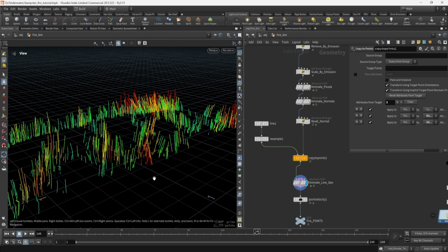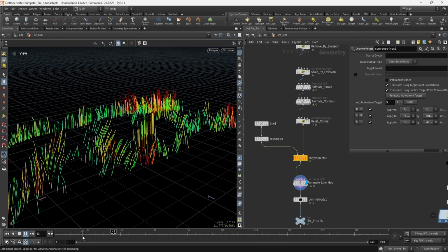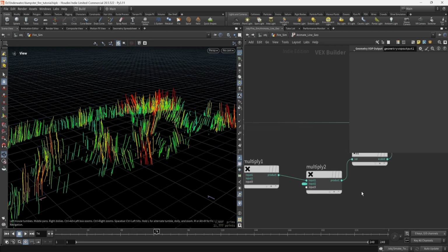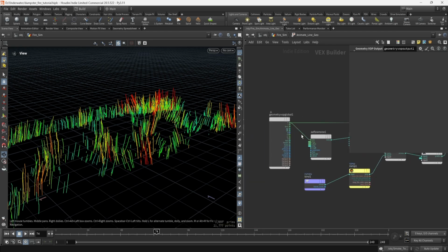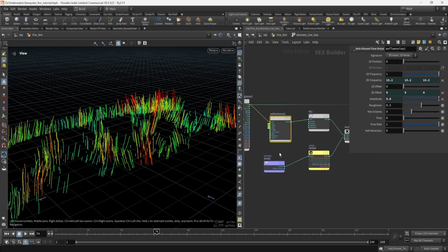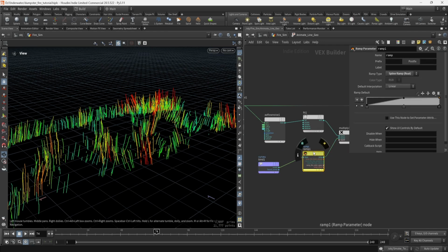If I play, if you look closely, you can sort of see those lines get turned around and a little bit nastier here. So that's going to animate the position of each point on this line as they play. And to do that, we're just going in here, similar pattern, right? We are going to take the point attribute, we're going to put it into a flow noise. We're going to use this curve U value here to attenuate the noise. So what this does here is we take our curve U in a bind node, we ramp it so that we can control where we want this to have, we're going to remap this to be not exactly linear 0 to 1.